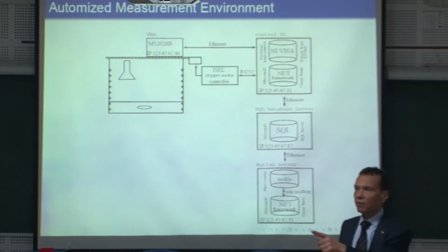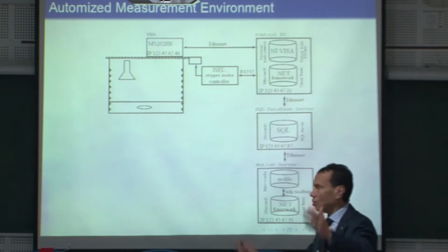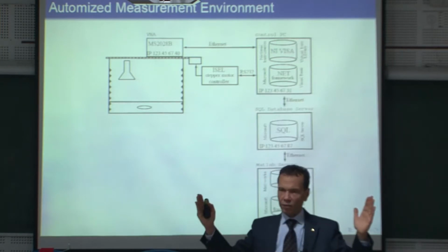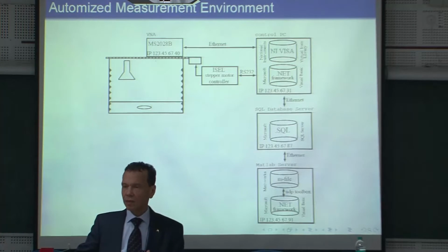Okay, this is actually a block diagram of your mix down. I will show you: you have your measurements in a bandwidth. You mix down in order to have it in the baseband. You can mix down either digitally if you have a fast digitizer, so digital down conversion.